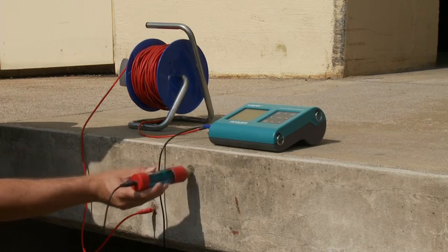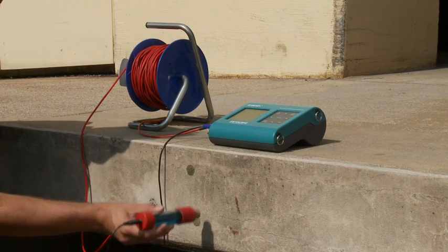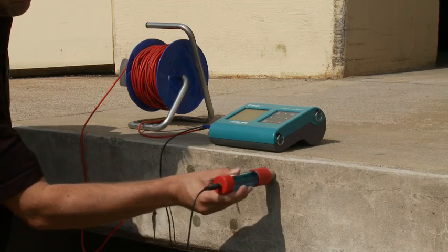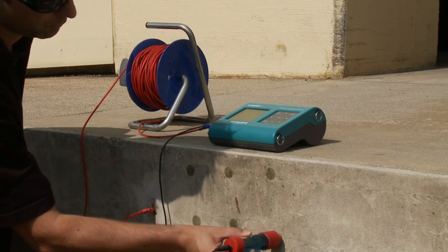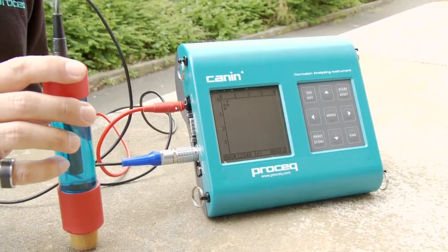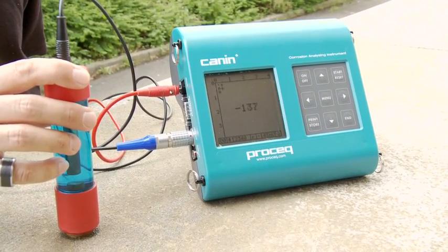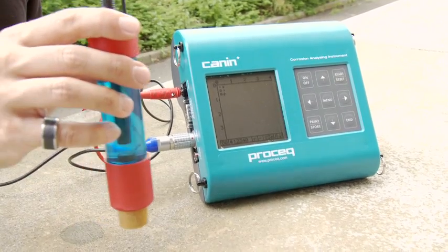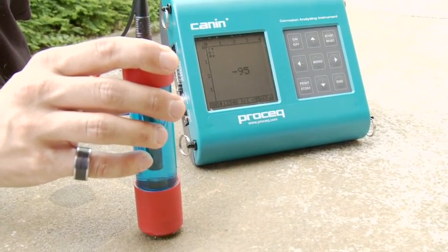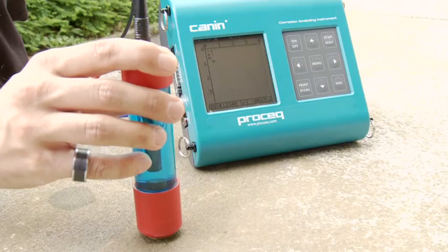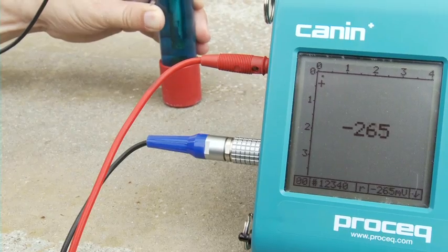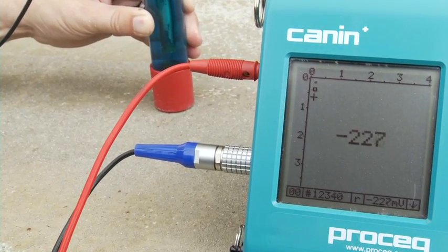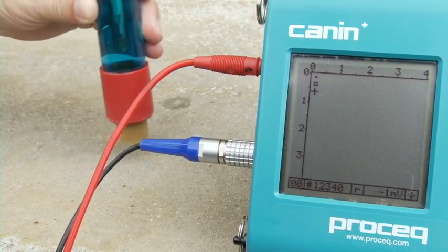To perform a measurement with the rod electrode, moisten the foam rubber plug of the electrode with water and press it lightly onto the first measuring point. The measured value will be shown in millivolts in the center of the display. Once it stabilizes, a beep will indicate when the measurement has been acquired automatically. At this point, the millivolt value is blended out and a grayscale indication will be placed on the grid. The cursor will move to the next point to be measured.